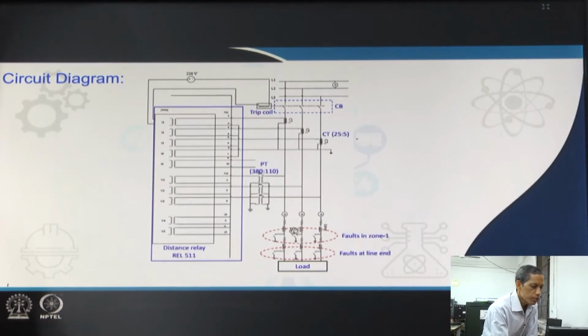Therefore, the Zm value between phases here happens to be 0, and that is the reason the zero sequence impedance of the line becomes equal to the positive sequence impedance of the line, which equals the negative sequence impedance of the line. These three phases are connected to the loads.